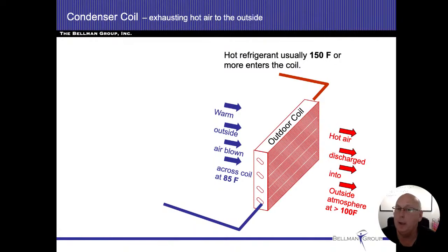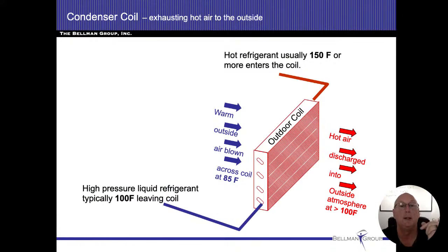And I did leave that off indoors. I want you to remember that air conditioning systems typically have a 15 to 20 degree temperature drop. That's a real simple, easy test to see if these things are basically doing what they're supposed to be doing. We turn the air conditioning on. If it's 70 degrees in the house, we should expect it to be 50 to 55 degrees on the other side of the air conditioning coil in the plenum. Anything higher or lower than that could be an issue.